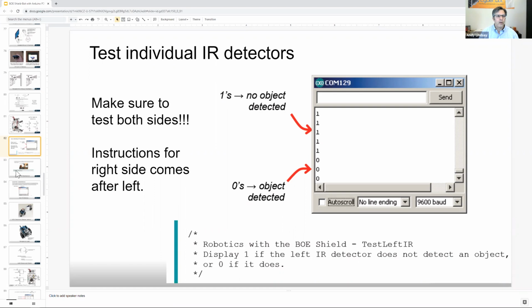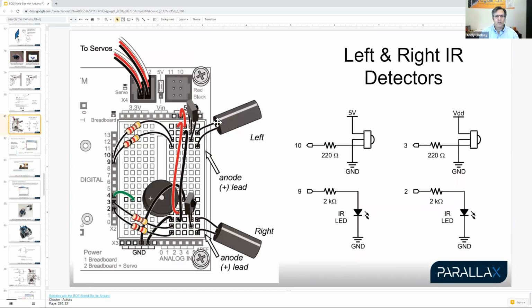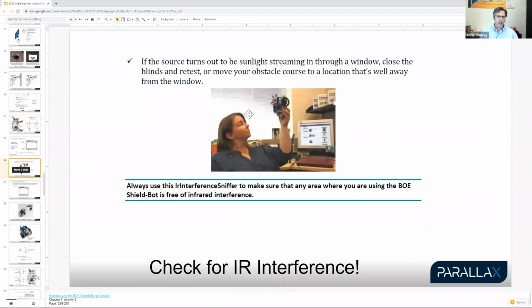And there's also one more test where you're just checking to make sure that the fluorescent lights in your office don't happen to be flooding with infrared information that's flickering at 38 kilohertz, because that's what these receivers are attuned to. They're only supposed to see that when you send the infrared out and it bounces off something and comes back. But some fluorescent lights, the ballast in those causes the light to flicker at that rate. It even makes a sound at that rate, and it's thrown monkey wrenches into ultrasonic object detection as well.